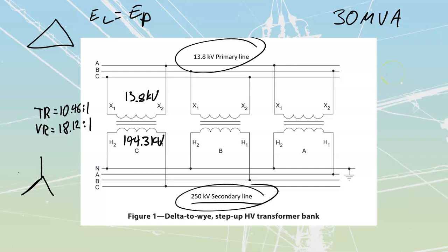Let's place that onto our lines over here: 1,255 amps. We know that our primary is connected in this delta, which means that our phase value of current is going to be less, because our line current is coming in and then splitting up across these two phases.